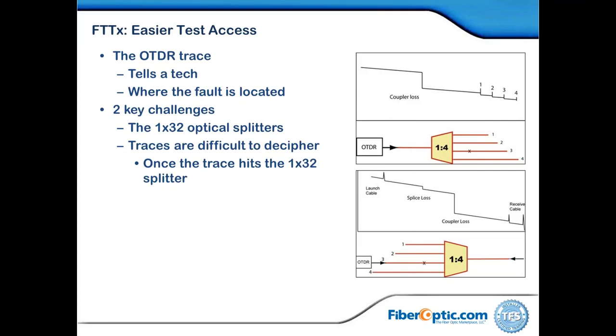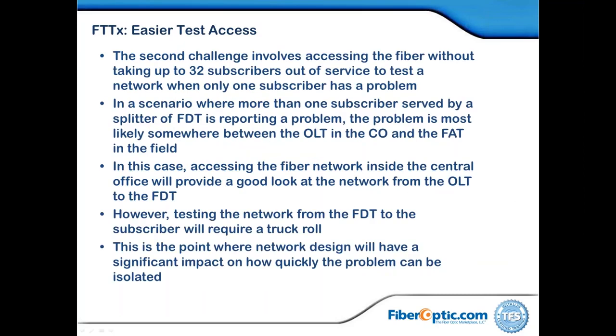So when you hear that you must have a PON OTDR, it's not so I'll see the same type of trace, but it does have some protection and some warnings that I am on an active circuit, as opposed to when I disconnected the circuit, and I don't have to worry about other users on it.